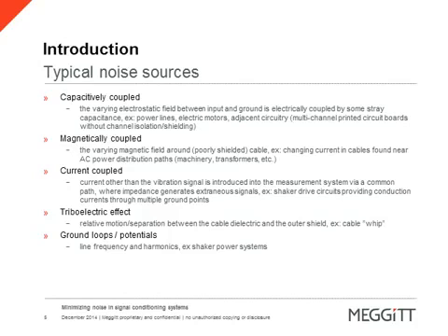Another form is the piezoelectric effect. It's caused by moving any cable during the test. So low noise cable is required for all piezoelectric accelerometers, along with proper grounding techniques, which is our main purpose for this presentation. So, ground loops. Ground loops are the most common type of noise, and that's why we're having this presentation.